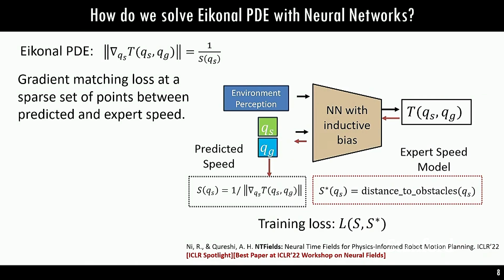We randomly sample robot configurations and their distance to constraint or collision, in this case. Then we use that constraint function as an expert to train our model, because our neural network gradient leads to an approximation of the constraint function, and then we compare this approximated constraint function with the actual one. Does that answer? So theoretically, it all sounds simple, but when we actually applied this,